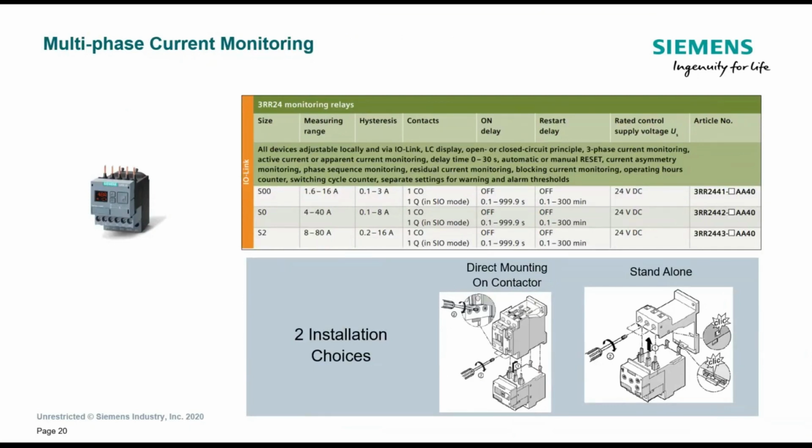So this will go all the way up to an 80 amp load and connect either directly to the bottom of a contactor, or we have a standalone shoe adapter. So if you wanted to retrofit it into an existing application and don't want to change out your contactor or any of the other equipment on your panel, but now you want some visibility into some good diagnostic and analog data, this is a great solution for retrofit applications for not only inductive motors, but also for resistive lighting or